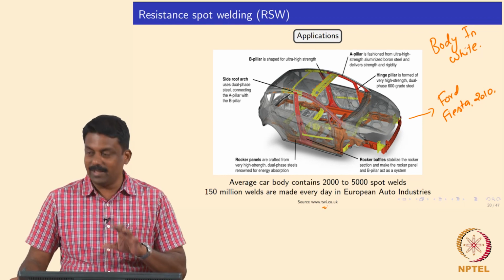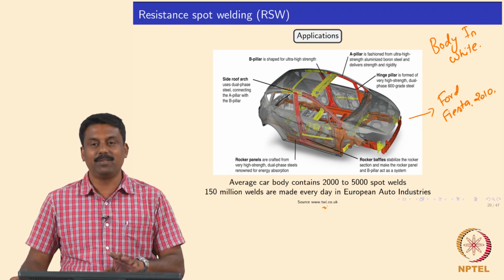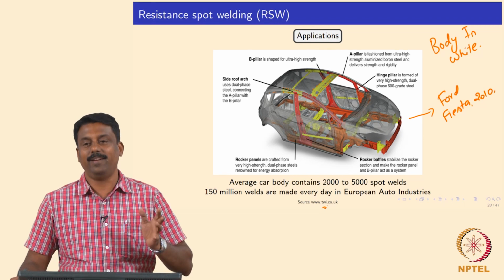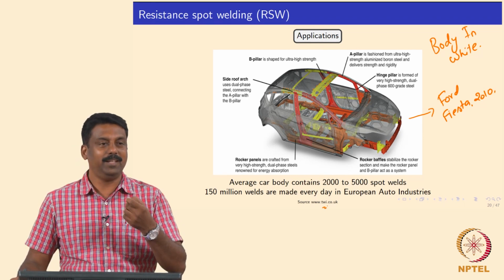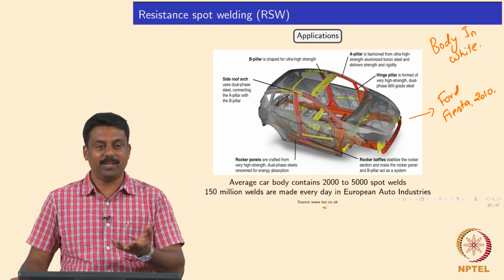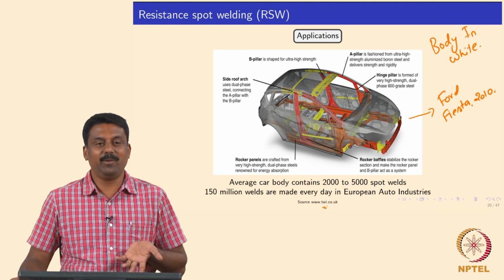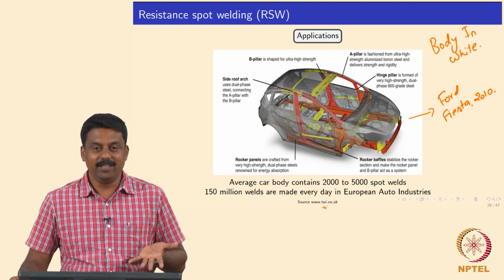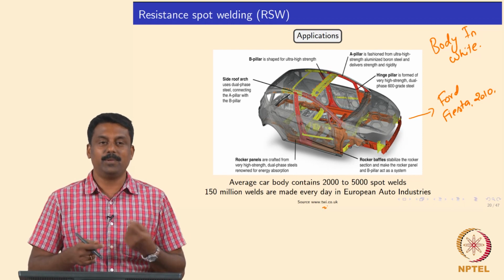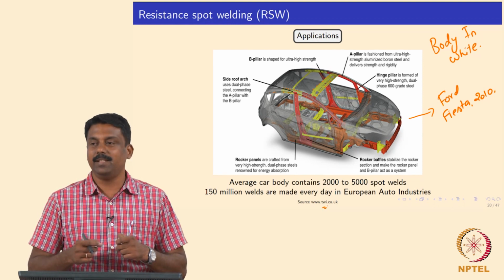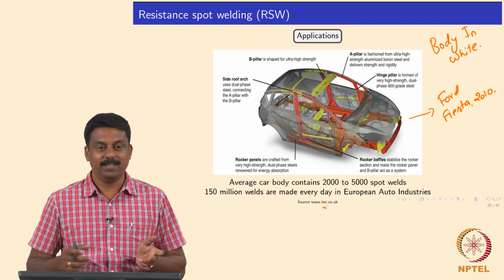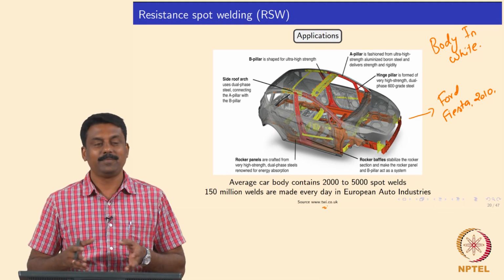By nature, the resistance spot weld is one of the worst geometries you can generate, because of the weld segregation and the notch effect. This is the worst thing you can have, but we will have to live with that. So, we will have to identify the weld thermal cycle which can give us improved mechanical properties. Okay. It is always the welder's job.